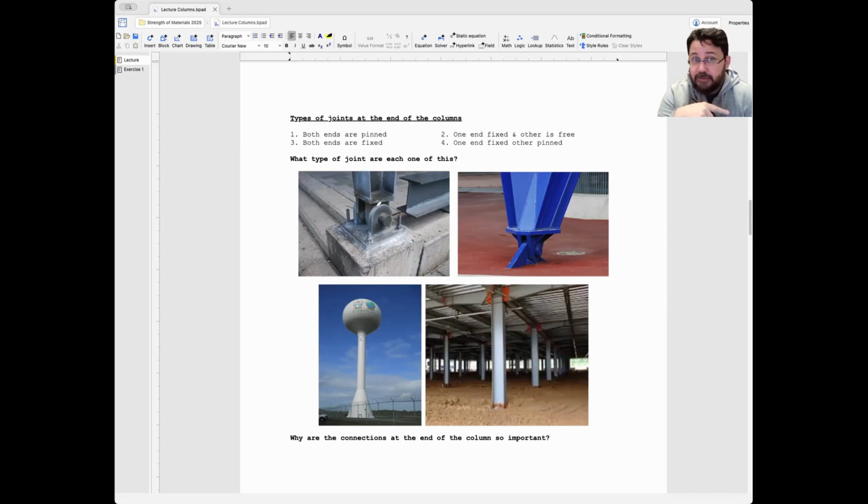And what surprised me, something that I told you in the last lecture we had, well, two hours ago, is that shear stresses sometimes you can just forget about them. Look at the size of this column and look at the diameter of this shaft here. Sometimes these are massive columns with massive weight, yet the diameter of this shaft or pin, this cylinder, is ridiculously small by comparison. You say, why? Well, it turns out that shear stresses caused by that load are so small that you can use smaller diameter pins there and nothing is going to happen.